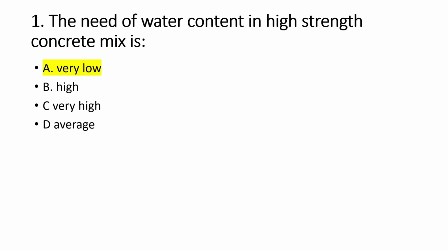The first important question is: the need of water content in high strength concrete mix is. Okay, so we know the need of water content in high strength concrete is very low. As the water content in concrete mix increases, the strength decreases, but the workability of the mix increases. So for high strength concrete we use admixtures such as plasticizers and super plasticizers, along with a very low water cement ratio. So option A is correct: the need of water content in high strength concrete is very low.